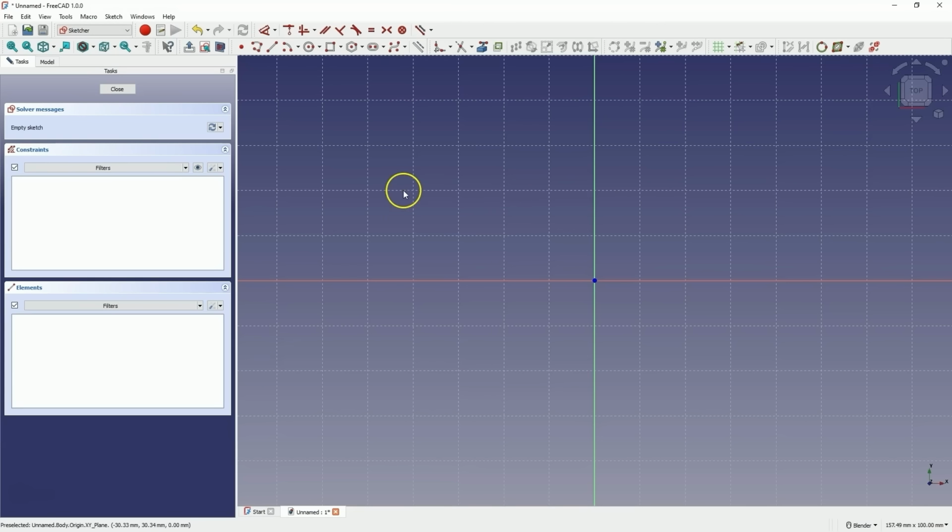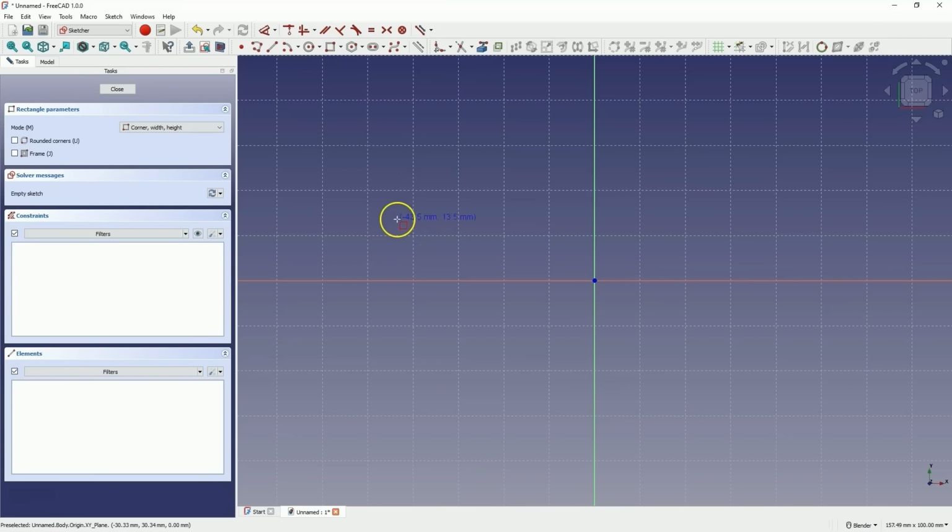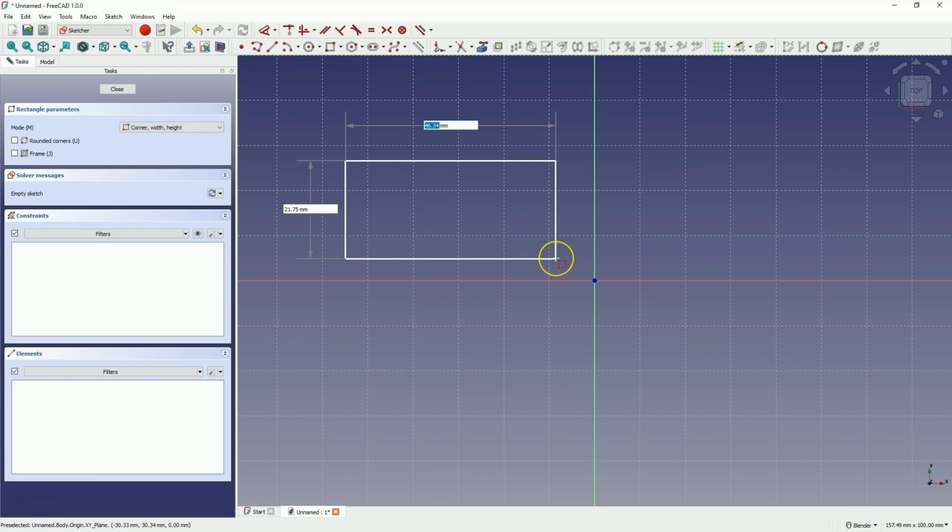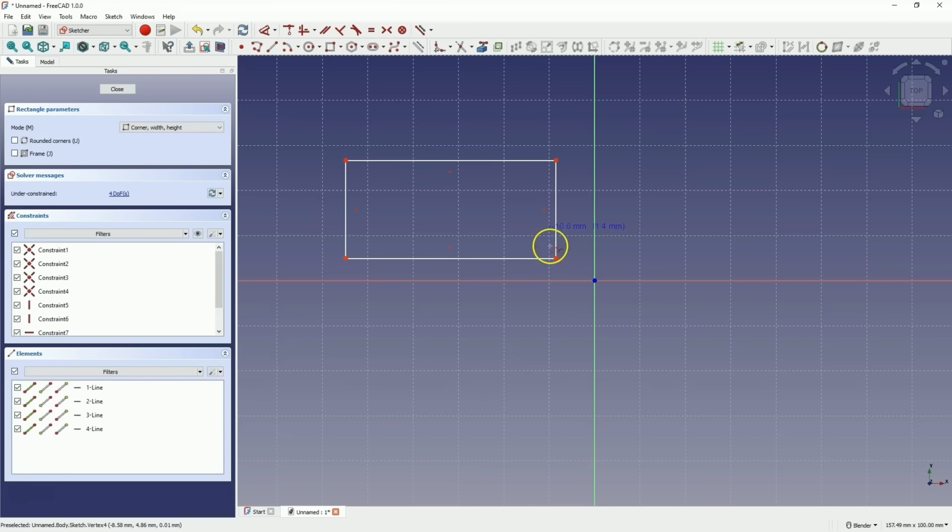First, I will draw any rectangle. I select the creation of a rectangle, and when it comes to drawing a rectangle, we need to define two vertices of that rectangle. When drawing the rectangle, we can immediately specify the dimensions of that rectangle, but I haven't done that yet. I have drawn a rectangle here, and the command to draw a rectangle is still active. I simply point to two vertices of the rectangle, and I have drawn a rectangle.